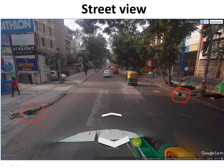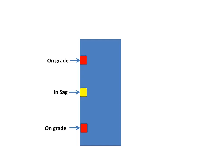The road grading is such that this is a sag point, and the rainwater runoff from the two sides of the road converges at this sag point. I have drawn this with a simple sketch. Here you can see there are two on-grade sections, on the slope, and from these two sides the water finally flows and accumulates at this location. What I have shown in yellow is the sag point inlet, where I am going to propose my sag inlet.